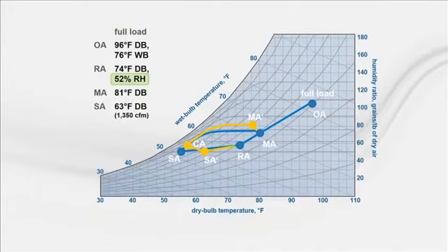Applying CDQ to our example, we can see that a CDQ system can get us back to the desired RH without the need for a cooler supply air temperature. In fact, our supply air temperature is now much higher, 63 versus 55 degrees before. For more information on CDQ and dehumidification systems in general, see the Improving Dehumidification in HVAC Systems Engineers Newsletter Live materials.